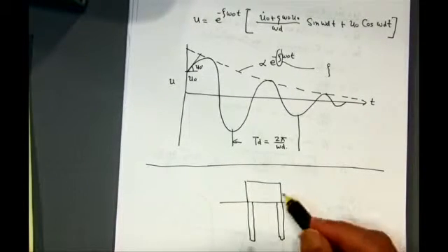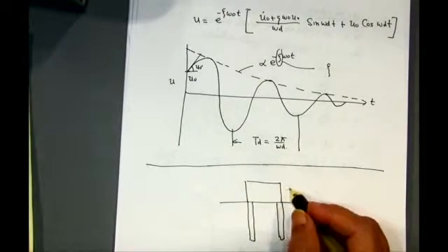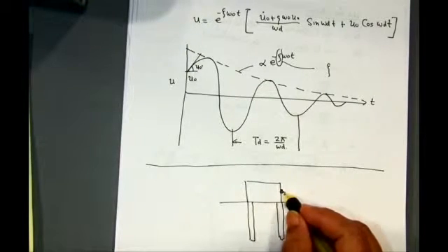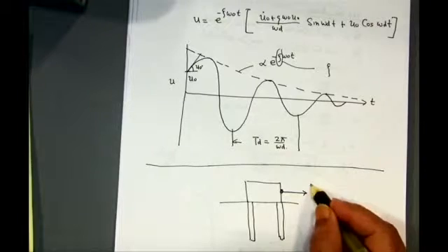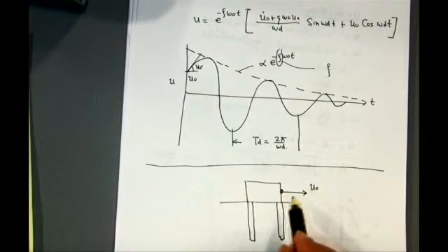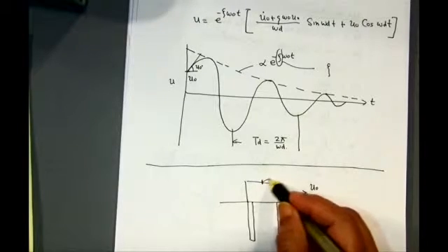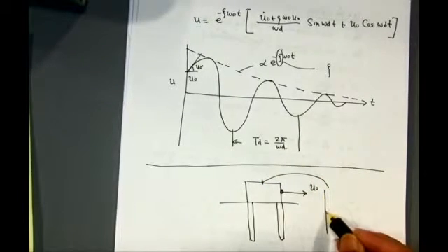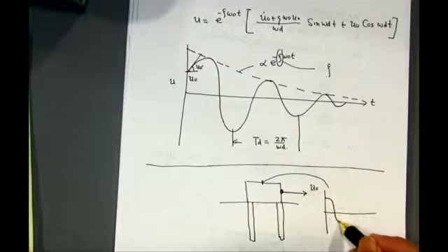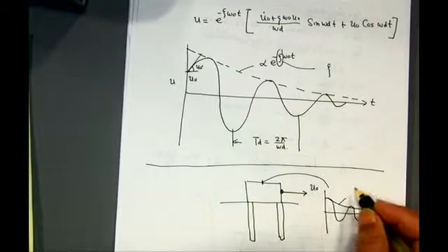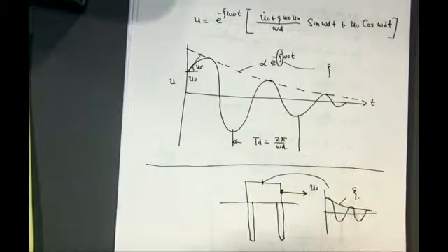So what was done in the field, we had a pulley connected to that. We pushed the system or pulled the system by a given displacement, and we let the system vibrate, and we had a sensor. So we were recording the time decrement response of the system, and from that we calculated this curve, and from that we could calculate the value of z.